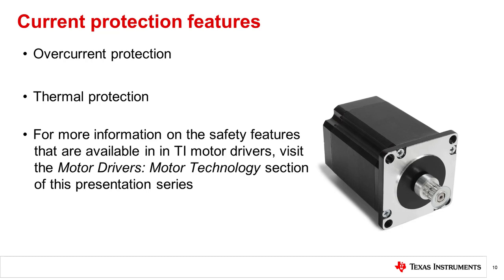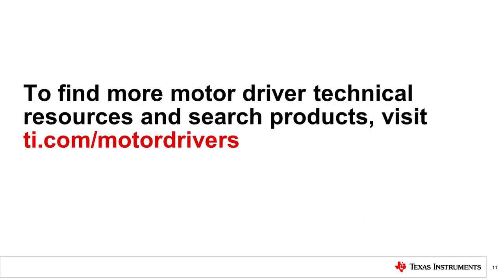Another protection feature in TI's drivers is thermal protection, which is related to RMS current. If the motor driver begins to heat up to dangerous levels, possibly due to a high current event, TI's motor drivers have a built-in protection feature that will shut down the device to prevent damage. For more information on more of the safety features that are available in TI motor drivers, visit the Motor Drivers Motor Technology section of this presentation series.